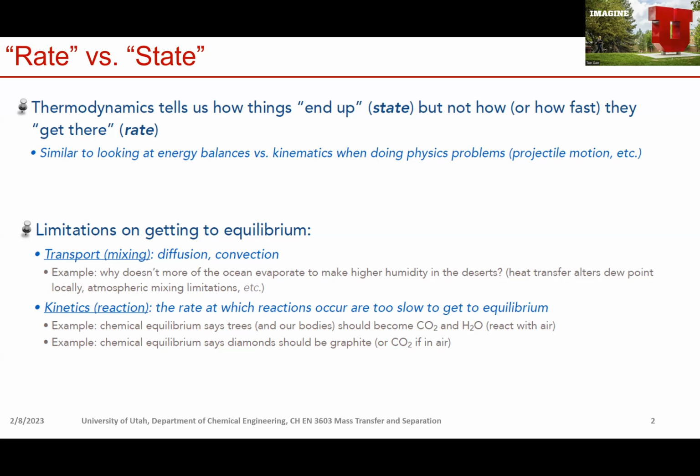That's because the transition from diamond to graphite is fundamentally limited by how fast the carbon atoms can move around in a solid state, which we know is extremely slow, right? We talk about diffusivity, and we know that diffusivity really depends on the density of your phase.